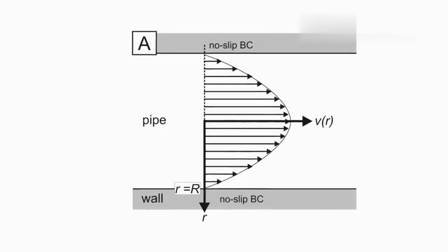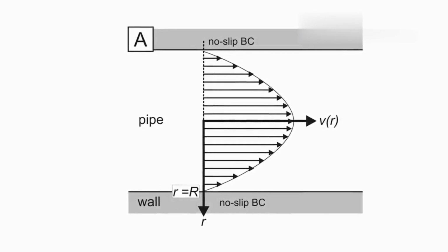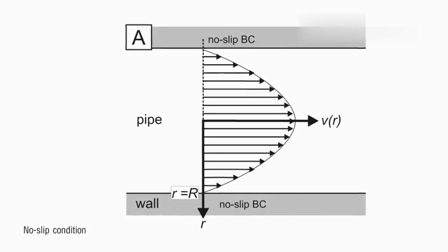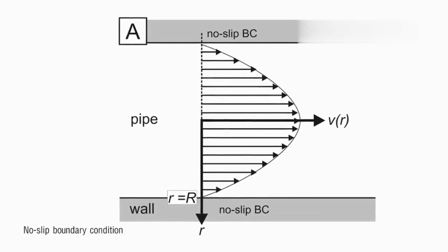The motive force of the Tesla turbine is an incredibly interesting phenomenon, known as the no-slip condition, also called the no-slip boundary condition. Let's explore the following experiment. A dark ink is pumped to the bottom of a flowing stream of water through a glass tube. While the majority of the ink is carried along by the flowing water, a small amount remains unaffected and forms a stagnant layer near the bottom. This is the phenomenon of the no-slip condition.